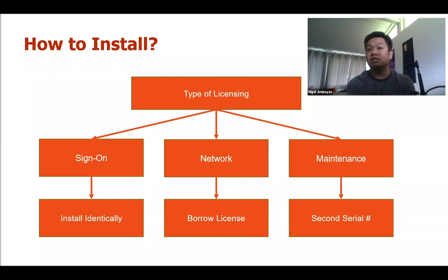If you have network licensing, and a lot of our customers do, essentially that's multi-user licensing. You take a license from the network pool, which is generally on a server, and you use it, right? And when those licenses are not available, you can't get a license. But how do you use that from home if you don't necessarily have access to the network? Well, there's an option in there called license borrow. And there's a lot of documentation about what that looks like.